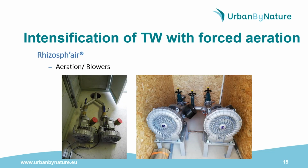Blowers generally used for this type of system are low pressure blowers operating at 200 millibars maximum, with airflows rarely exceeding 800 cubic meters per hour for a large wastewater treatment plant of 2,000 people equivalent, for example. So here on this picture you can see this kind of blower, which is generally installed in the technical room.